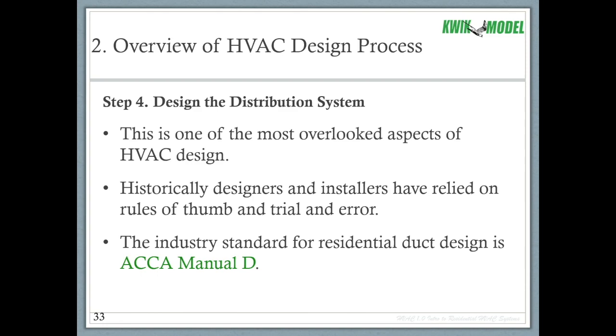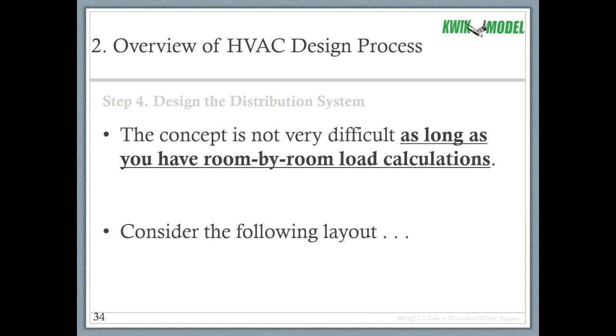Historically, installers have relied on rules of thumb, and trial and error is another way to design a system: oh, it didn't work this time, let's fix it next time, let's put in a bigger system next time. So you'll see a lot of that as well. The industry standard for residential duct design is ACCA Manual D. The concept of ACCA Manual D is not very difficult as long as you have room by room load calculations.